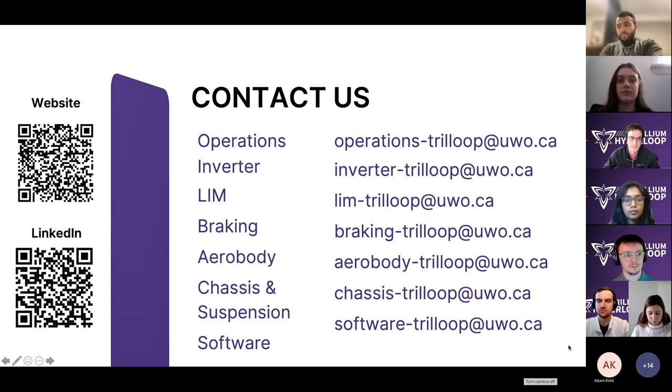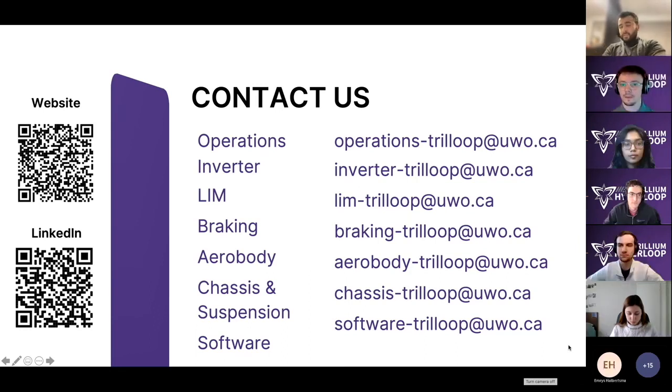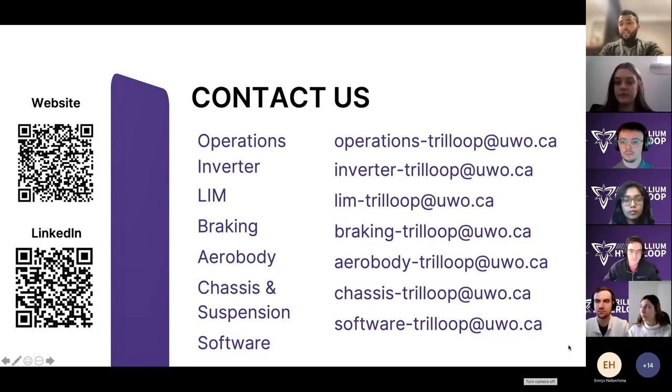This design was proposed by one of the professors at our faculty of engineering. This exact design is implemented at Western University for a different application. We were advised to use this form of actuation to dampen the vertical oscillations that could occur. Given that the flywheel is geometrically proportionate, there should be no forcing factor to make it vibrate. But just in case, the hydraulic pistons have a really high stiffness, enabling them to counteract any oscillations. Does that answer your question?